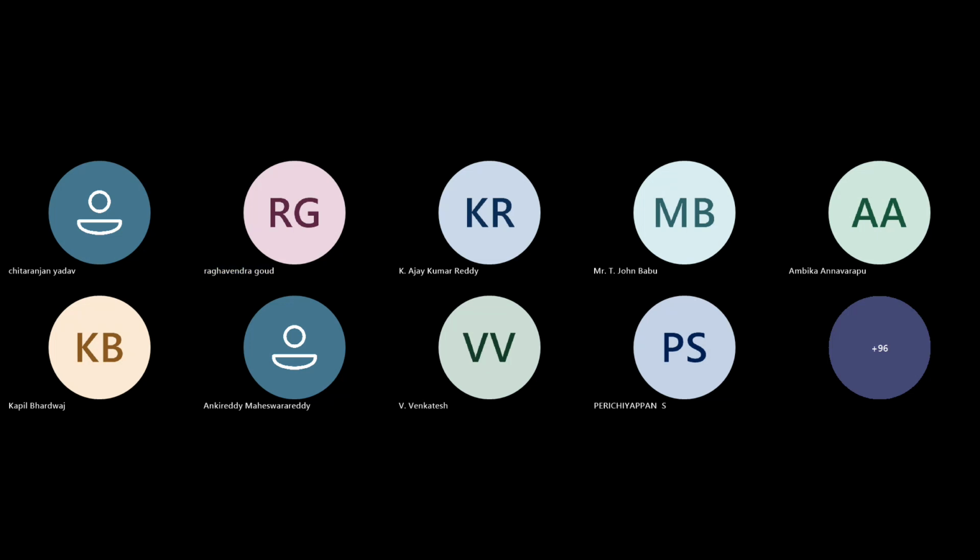Same thing, sir. I actually have that objective, like blending of ceramic powder like hydroxyapatite or TCP with polymer. Yes sir, we can. Coming to the printing of the composite that you would like to use, the printability of the material is purely connected with the particle size of the respective ceramic material and the type of binding polymer material you would like to use.